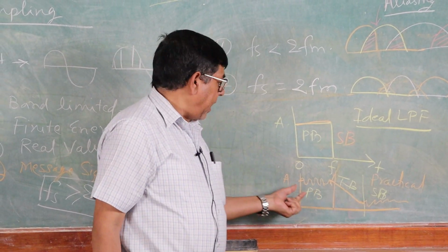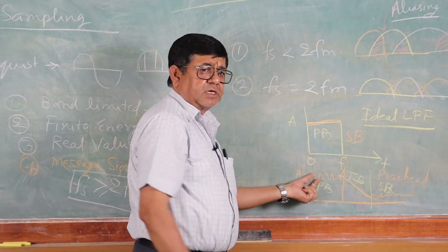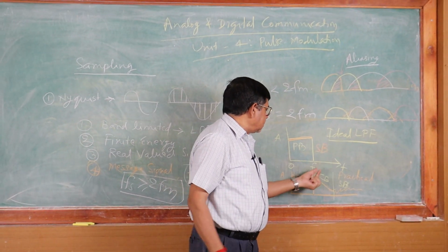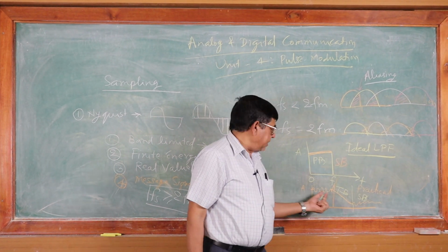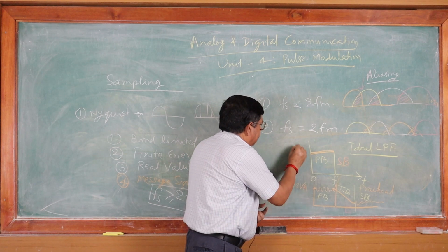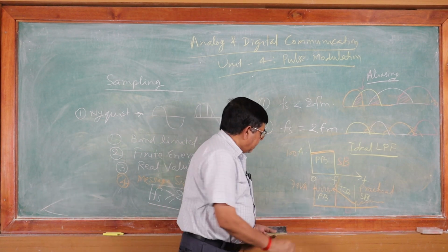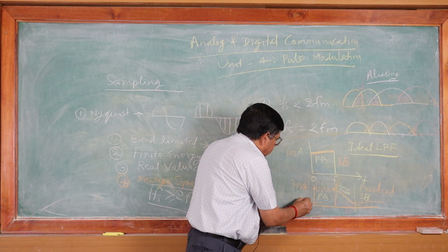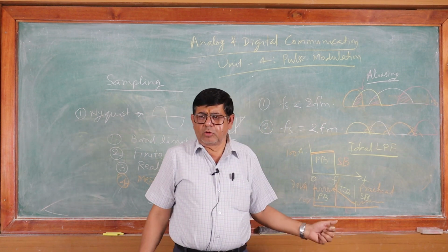And this is constant amplitude. Here there is no constant amplitude, there are ripples. Here also this is constant 0. Here it is not 0, it is 10 dB. Let us say this is your 70 volt. If this is 100 volt, then 70 volt is permitted, which is 3 dB. And here minus 1 dB, up to 10 volt is permitted. 10 volt is considered as low voltage or no voltage.